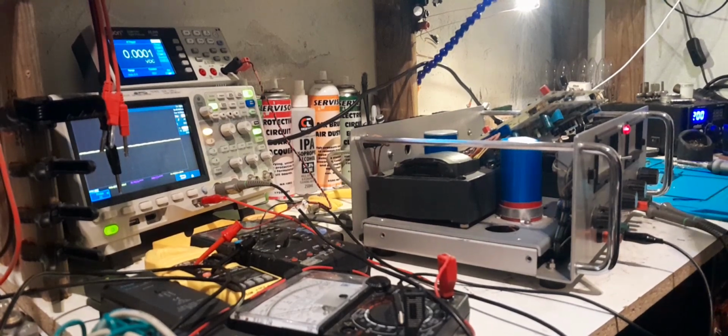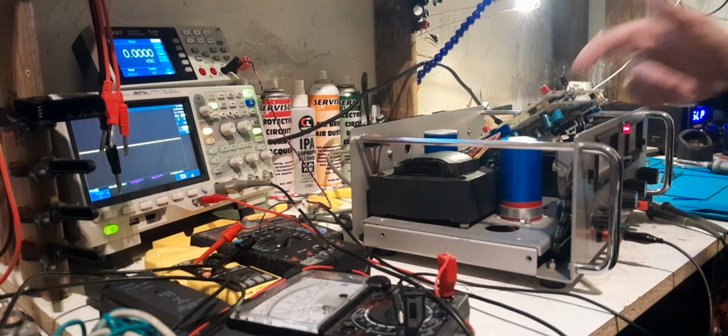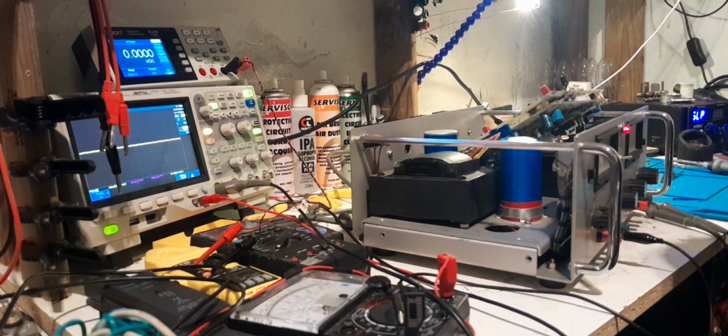They can be faster or slower than the LM301 technically. It depends on your compensation. And I don't just mean resistors, networks, capacitors. I don't just mean the compensation capacitor you might have across your input pins, or an RC network between the output and the input, or even just a capacitor between the output and the input. I'm talking about also the compensation capacitor in the LM301, the external comp capacitor.